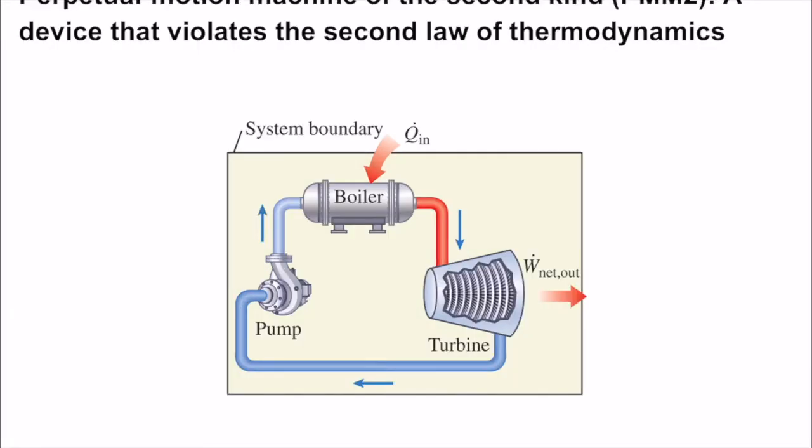Okay, my answer is that this system does not make sense at all because it violates the second law of thermodynamics. The statement about the second law of thermodynamics we just learned is that there is no such device that has the thermal efficiency of 100%. If you look at this system though, you only have one heat input that is entirely converted to net power, net work. Okay? So based on this claim,